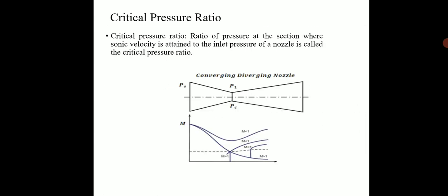As the steam expands in the nozzle, the pressure and temperature drop, and the steam starts condensing when it strikes the saturation line. But due to the high velocities, the time for which the steam resides in the nozzle is small, and there is not sufficient time for heat transfer and the formation of liquid droplets due to condensation. These are the flow of steam through nozzles. Now the critical pressure ratio.